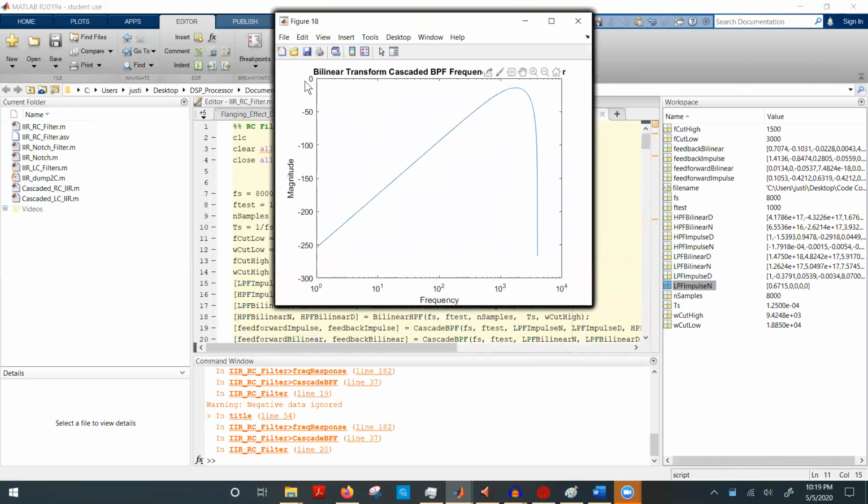Since those two filters intersect very narrowly, even though we might be in the pass band of the low pass filter, we would still be slightly attenuated by the high pass filter. So we're never going to be able to get exactly a gain of 0 dB or 1.